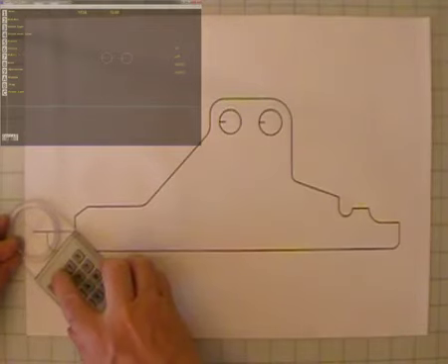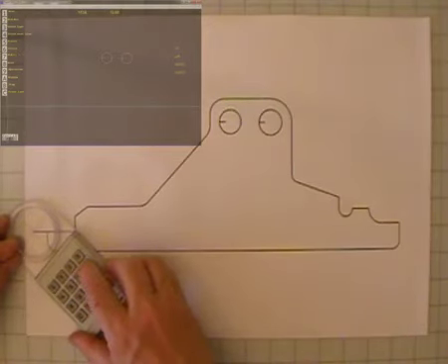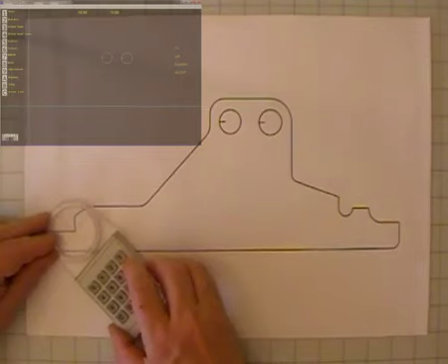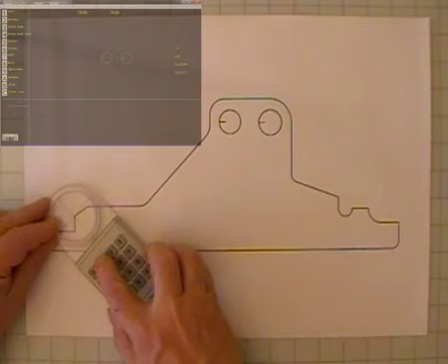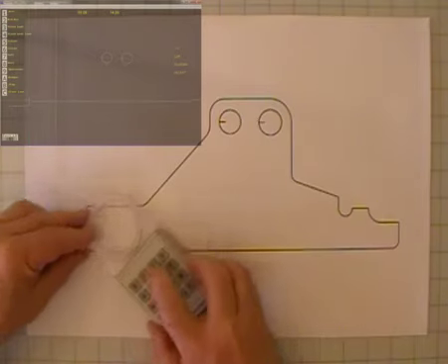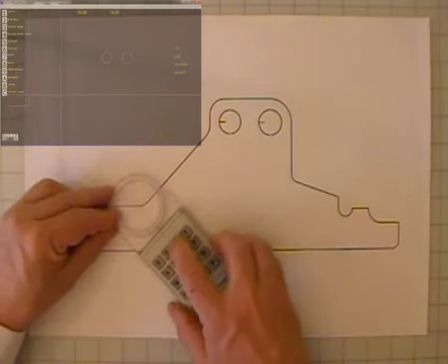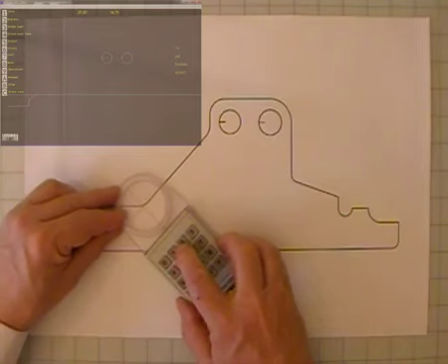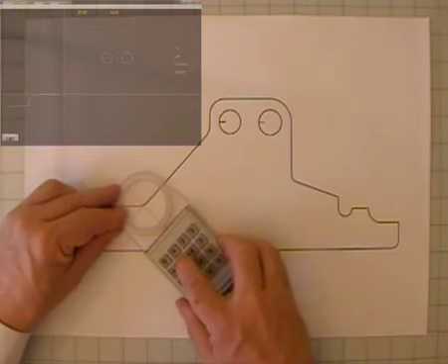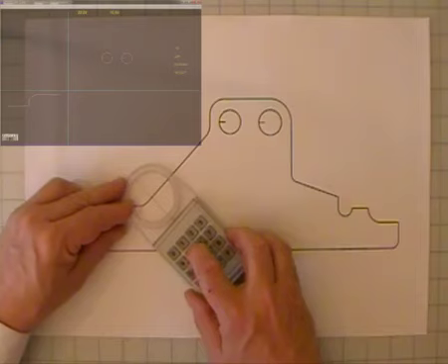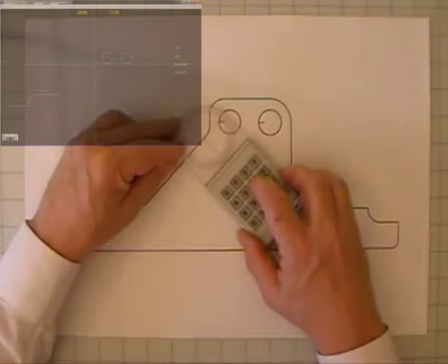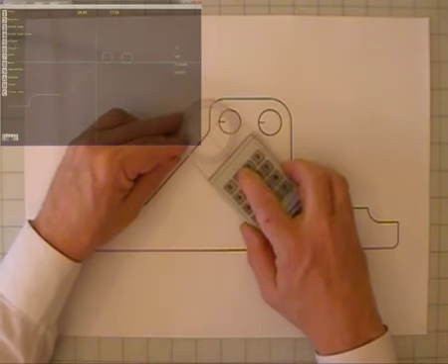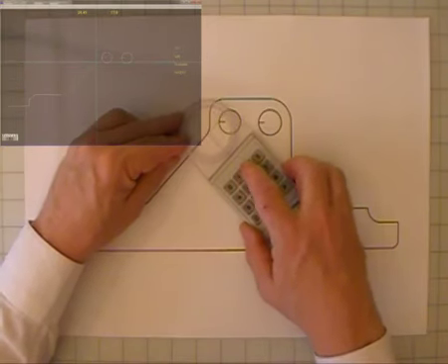Across to the outside profile, we will cut in a clockwise direction using a series of button 1 presses for lines. Use button number 5 to pick up the fillet. The number 5 has to be on the arc. Exactly where is not critical. You see how fast this is and how accurate.